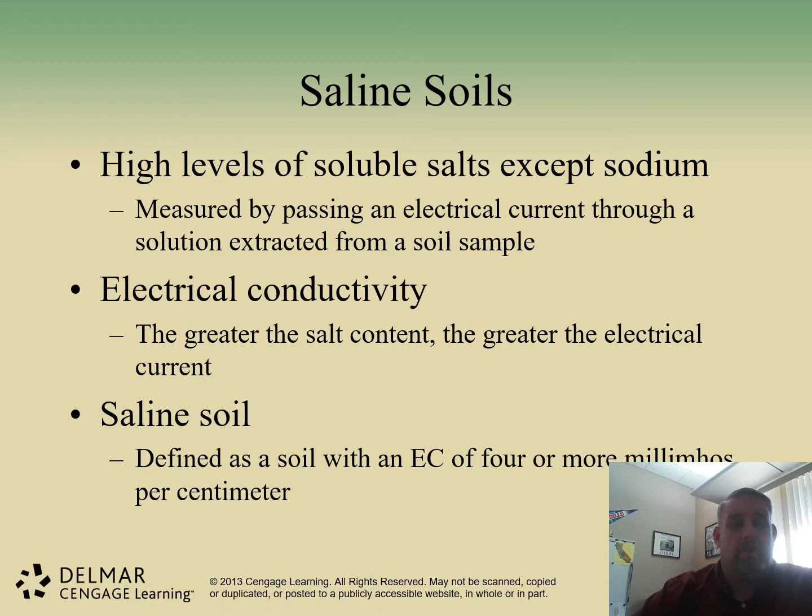Saline soils include high levels of soluble salts. These are measured by putting electrical current through. That's going to be your electrical conductivity report, or EC. And the more of these salts that are within the soil, the greater your EC will be. And this is how you can determine how many total dissolved solids you have within your soil.